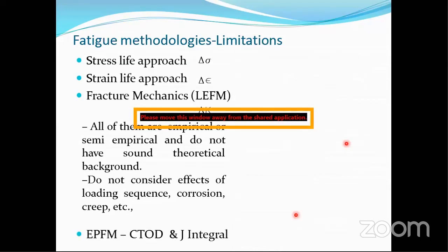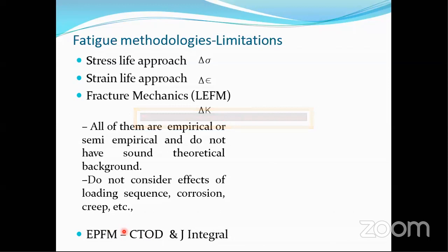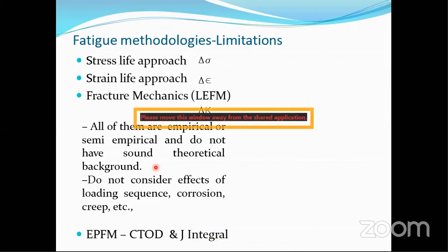There is one more criterion called plastic fracture mechanics, where the plastic zone size is also considered along with the elastic zone. That is, plasticity at the crack tip is also considered in this case. The parameters used to describe it are crack tip opening displacement and J integral. This is based on the energy approach. Since this presentation is more about fatigue, I'm limiting myself to LEFM, where it is more directly related to the elastic zone.